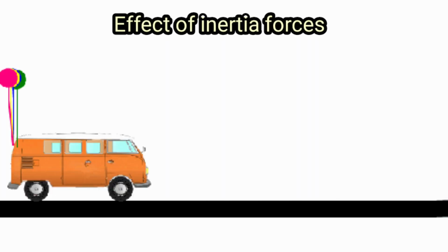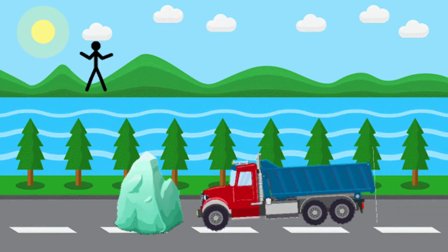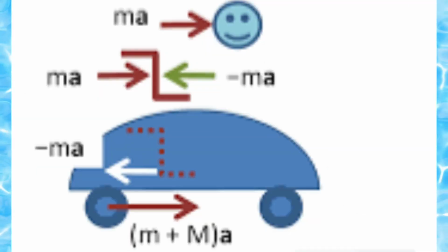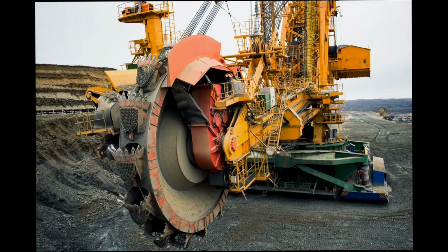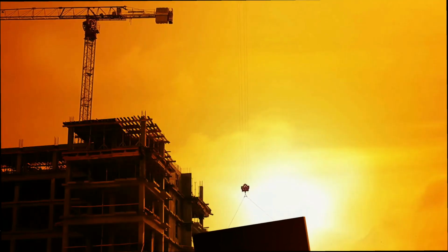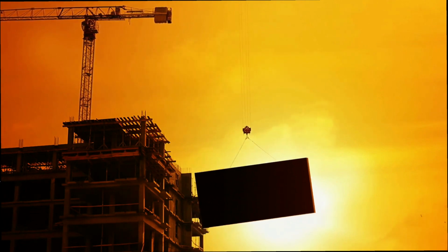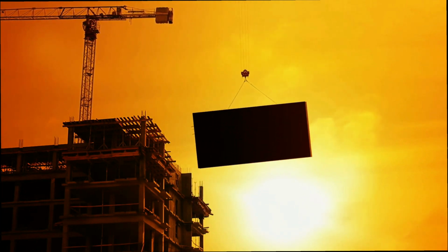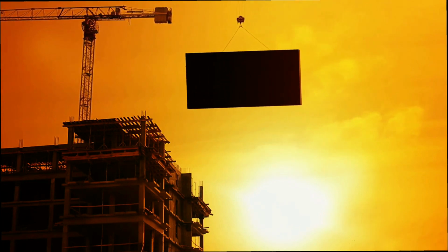If the components of a machine accelerate, inertia forces are produced due to their masses. However, if the magnitude of these forces are small compared to the externally applied loads, they can be neglected while analyzing the mechanism. Such an analysis is known as static force analysis. For example, in lifting cranes, the bucket load and the static weight loads may be quite high relative to any dynamic loads due to the accelerating masses, and thus static force analysis is justified.